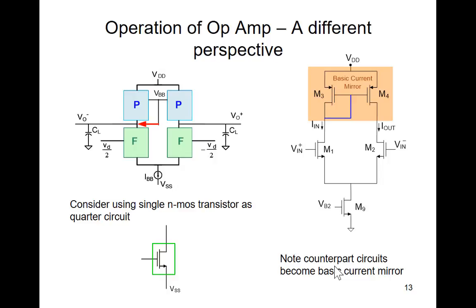Good observation. I like the thought process. We asked the question, what can we do to increase the gain? One thing we can do is to make the conductance smaller. The other thing we can do is steer more current to that node. Or both.